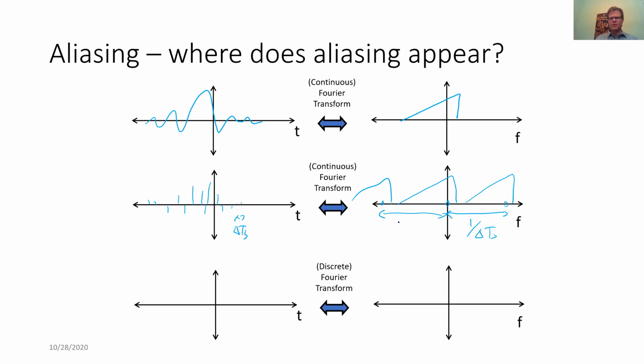And actually, interestingly, when we have this shifted object, recall what happens when we do the discrete Fourier transform is the only region that we see here is this middle 1 over delta TS. So we'll get an image that would look like this, where we would see aliasing, although aliasing that is not necessarily destructive, right? It's not overlapping with another signal. Okay, but you want to remember that the signal is kind of wrapping around to the opposite side here.